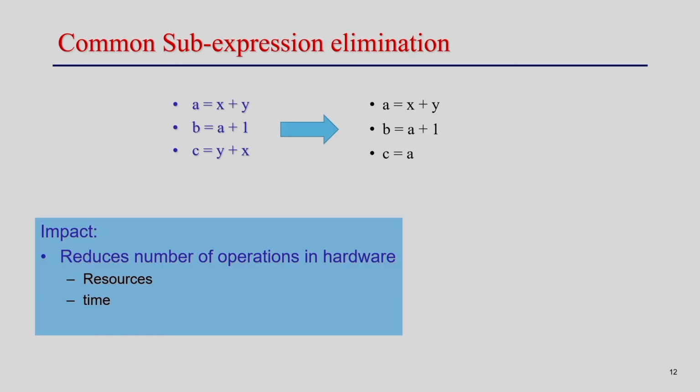The next one is the common subexpression elimination. As you understand from the name, the common subexpression, that means if you have subexpressions which are common, I just eliminate those subexpressions, right. So, I am going to compute it once and I am going to reuse it. So, for example, here you see x plus y and x plus y. So, basically y plus x. So, they are basically the same, but if you execute this code in the hardware, you are going to do this 2 times, right. So, I do not need to do that.